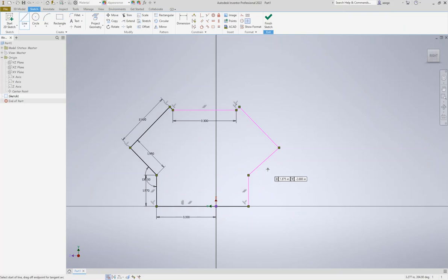This is the engine block outline, made of construction lines. All right, not engine block yet. It didn't become the engine block yet. We need a circle at the center. So we have the circle command, and we also need to draw a center line, which perhaps really helps.